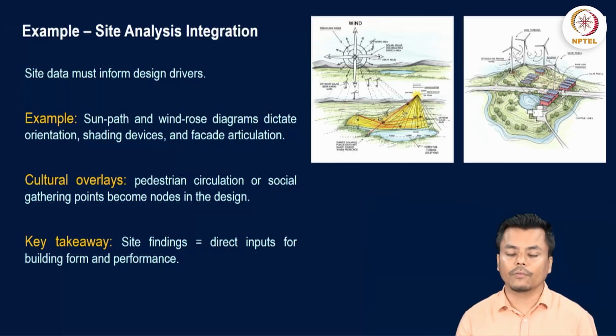If no other direction is possible, then you can think of how you can design your building and place your activities within the block in such a way that habitable spaces, or the spaces which will be utilized for the maximum number of hours within the usable time, are protected, so that these microclimatic factors don't hinder or impact the comfort within the space. So this information is essential for the project, and it will guide you in the design decision process.